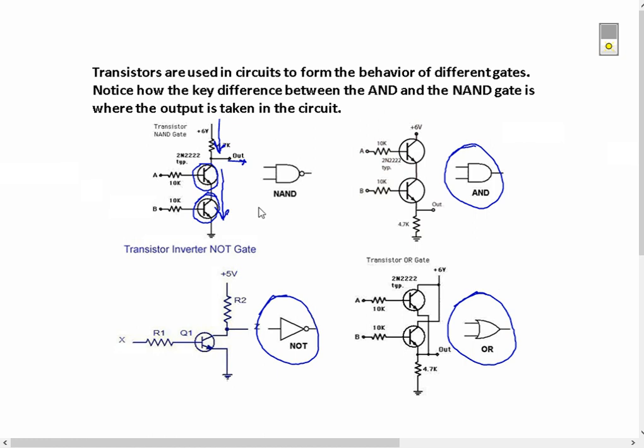One of the reasons we call this a NAND gate means not and, not in this particular case meaning that it's turned on by default. So normally the output will be 1 unless I turn A on and B on. When I turn A and B on, current's going to flow down. It's no longer going to have the voltage here, and it has the characteristics of a NAND gate because of that. Now, the AND is kind of exactly the same circuit, but backwards.